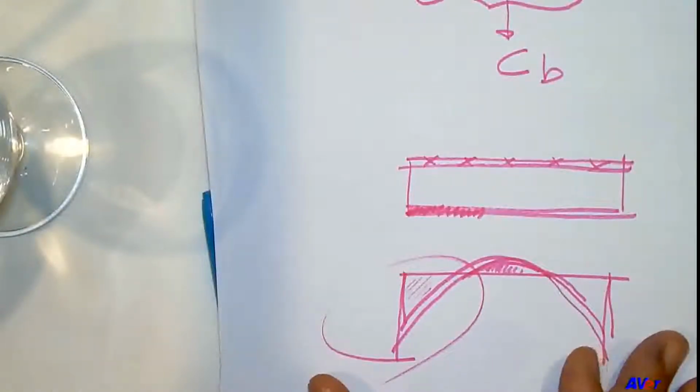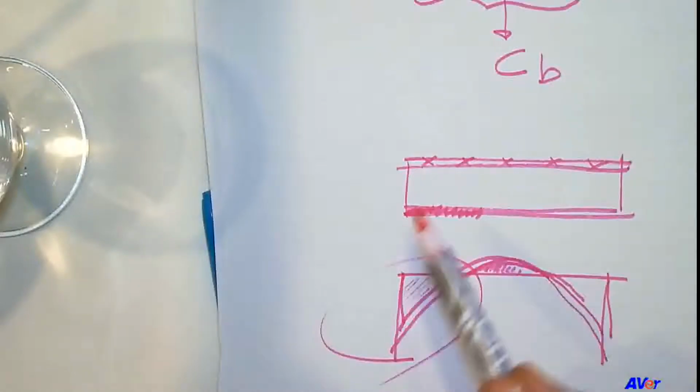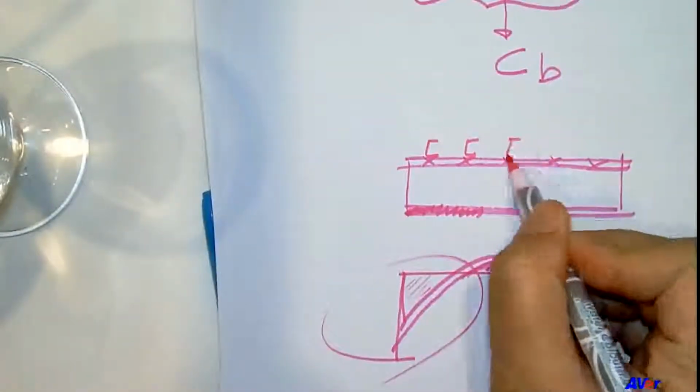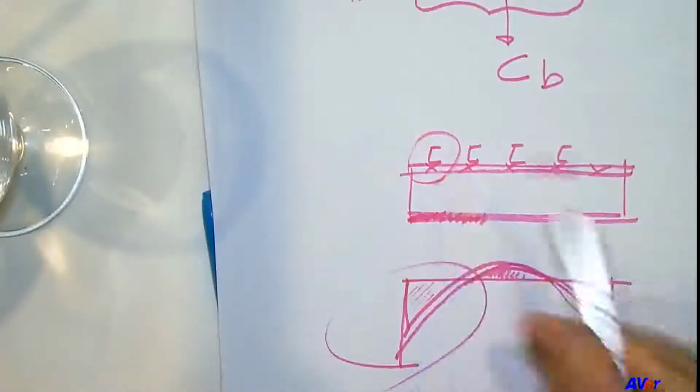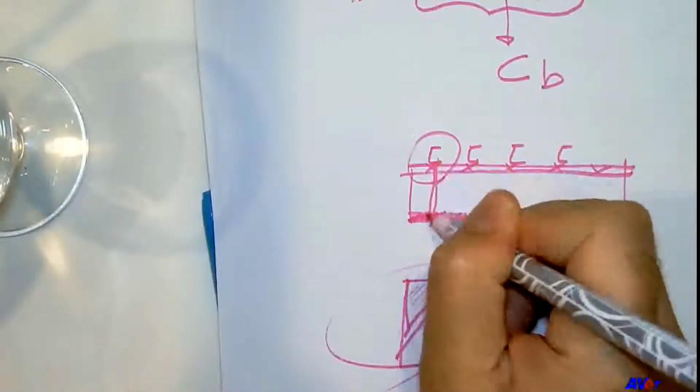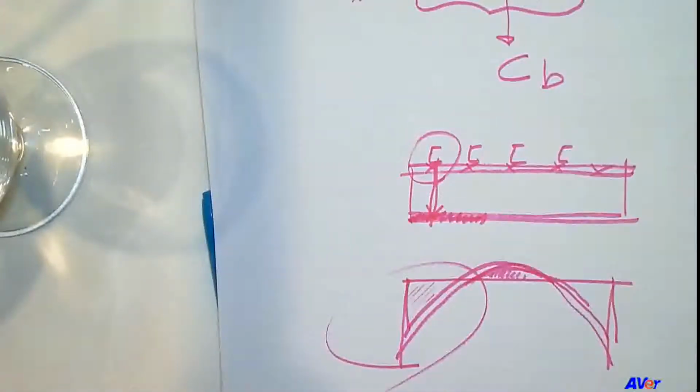All right? So like this case, if you have a beam like this and say, okay, you have some maybe small beams coming in on top, this will not help. It can only help when you provide a kicker coming down to stop your compression flange from moving. Right? And that's the idea. And now we are talking about the brace.